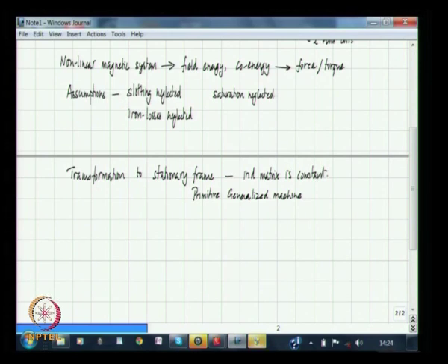We also saw that this machine could then represent a DC machine, a DC separately excited machine, or a series connected machine with or without interpole windings, and so on. All these machine varieties can be adequately represented by these equations in the pseudo stationary reference frame.